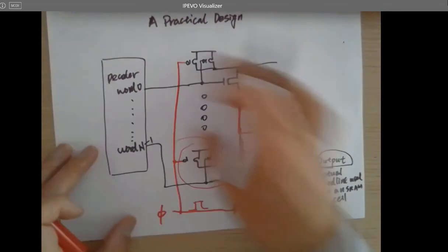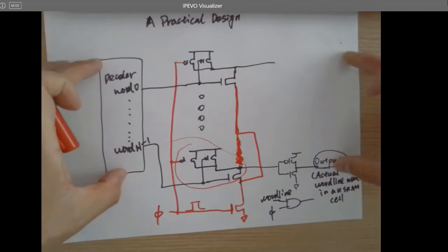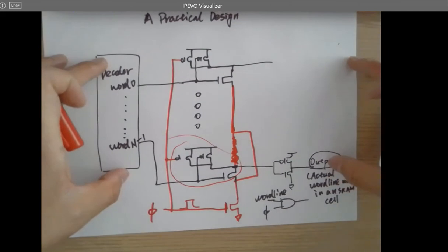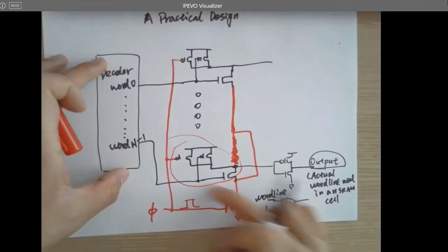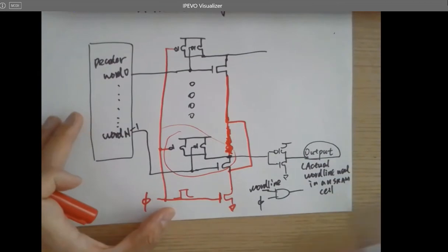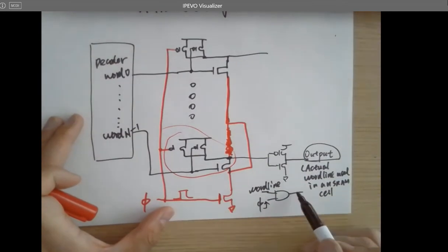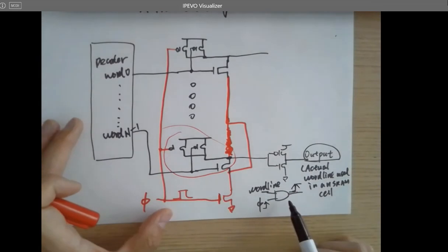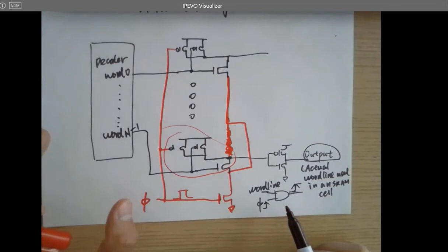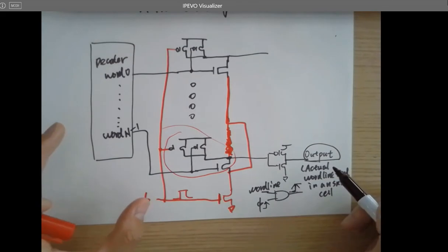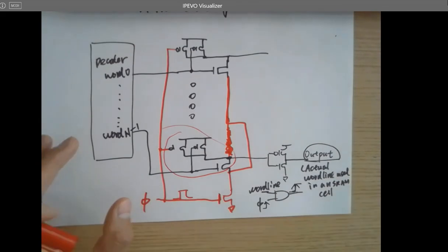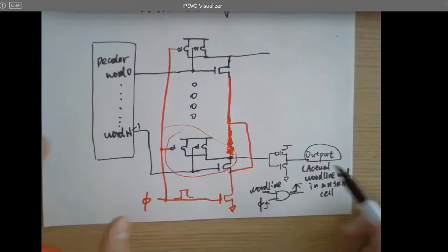And the reason we need this is the decoder and the SRAM cell in between these two components. I have a clocked circuit to enable it. So that's the word line. Whenever this is at the rising edge, it's going to send that word line data to here. So I can use a clocked signal to control the word line being shorted to the SRAM. A NAND gate being inverted, you got an AND gate, right?